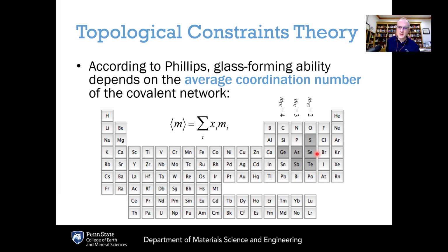And in case you're wondering what these chalcogenide glasses are used for, if you remember back to our second lecture on glass compositional families, chalcogenide glasses are known for their good optical properties in the infrared. Oxide glasses are usually very good for transparency in the visible. Then, if you go to larger and larger atoms, that low-loss transparency window is shifted to longer and longer wavelengths, or in other words, lower energies. So when you go from an oxide glass to a sulfide glass, that gives you greater transmission in the near infrared. As you go to selenide and telluride glasses, it pushes the transmission window further into the mid-infrared.